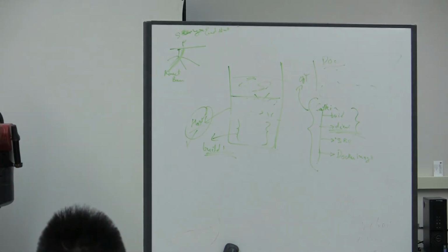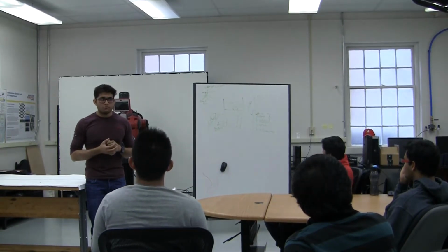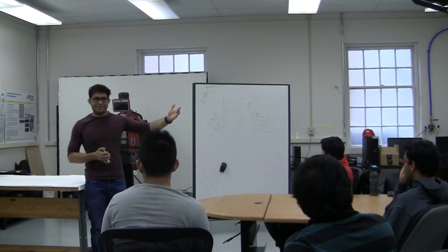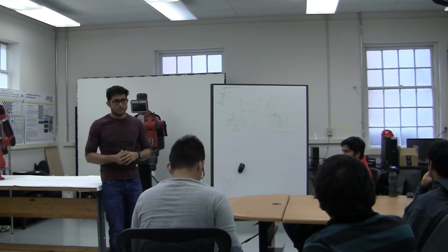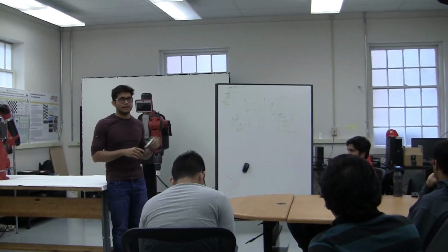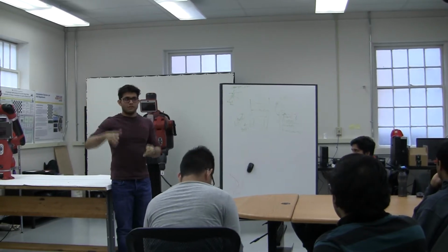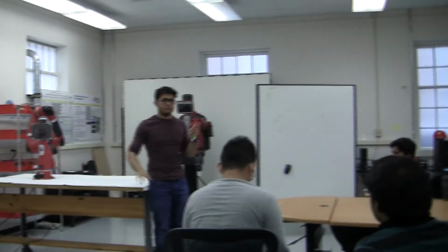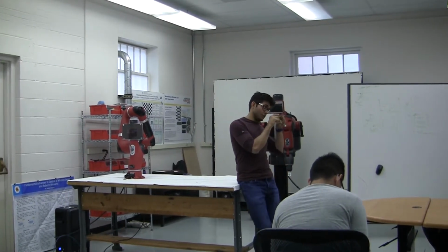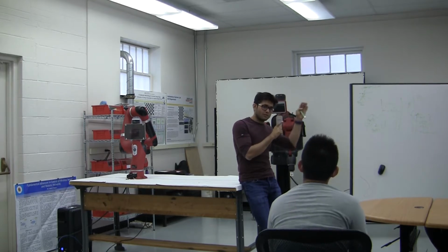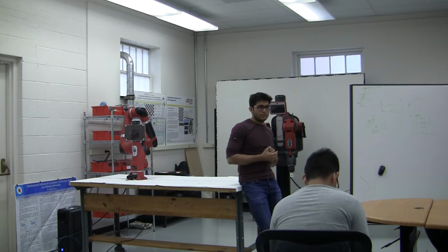It's okay. So that's why you use macro now. With URDF you have to edit the URDF, but now you don't have to edit it, you can just use macro and attach two URDFs together. It's much simpler. You call it like import macro, this dot macro, that's it. Import both macros now. You can call it and run that specific one. Now the new macro file that you created, run that macro with this. Now it's calling both of them, the connect and the robot URDF, and connecting them. That's how we do it.